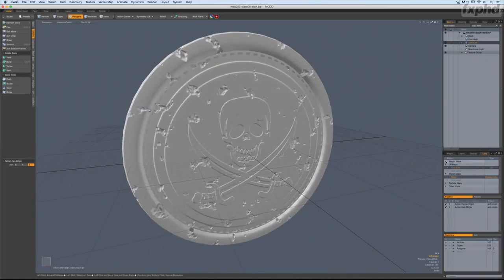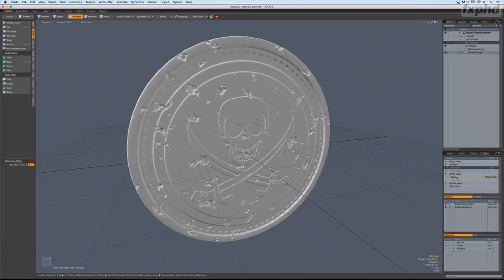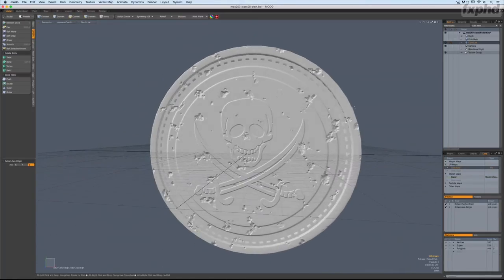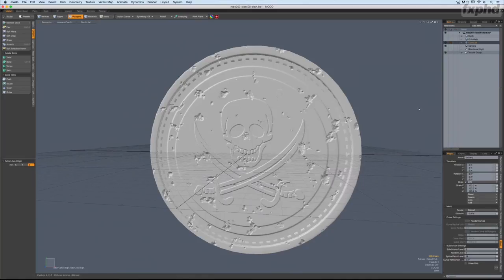Now, the cool thing about working with morph maps is that we can completely change and deform our geometry non-destructively. Notice that my morph map is selected. If I was to unselect it, you can see that the geometry goes back to its original form. So it's not permanent. It's non-destructive. Let's turn it off. And now let's go back over into our render environment. And actually, you don't need to be in your render environment to do that. You just need to go into your shader tree.